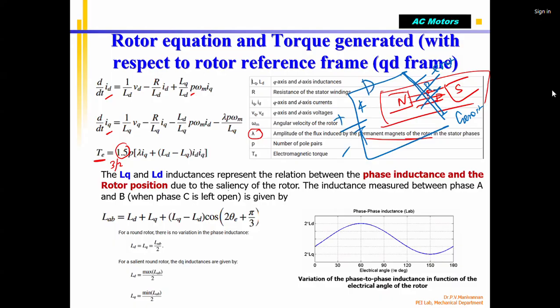There's a current flowing, and I'm supplying current. Automatically, one more magnetic flux is created due to current flow in the wire. Then this magnetic flux interacts with the already existing magnetic flux. This we call a field magnet or stator magnet. This is called a rotor magnet or armature magnet. So there are two magnets, they interact, and the force is created.